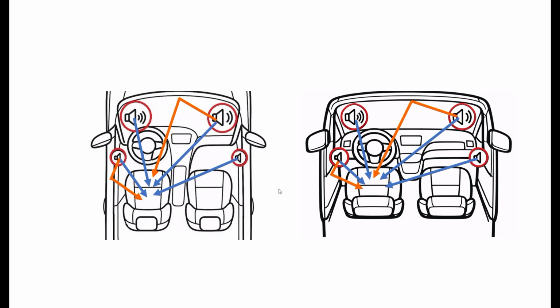Oh, but I can buy speakers with passive crossovers, right? Yes, some speakers come with passive crossovers, but all that is, is the crossover. It doesn't allow you to change the timing, it doesn't allow you to change the levels, and all that type of stuff. All it does is apply a crossover to filter out certain frequencies that the speaker is playing. You're largely still getting the speaker response that is a sum of your listening position and the geometry of the car and your speaker distances and all that type of stuff.